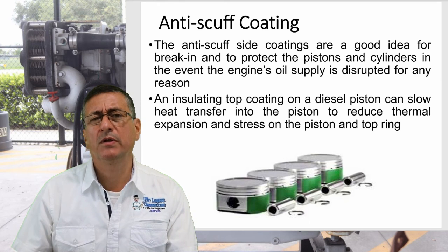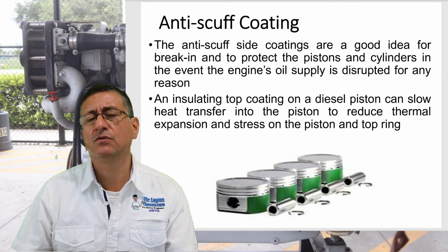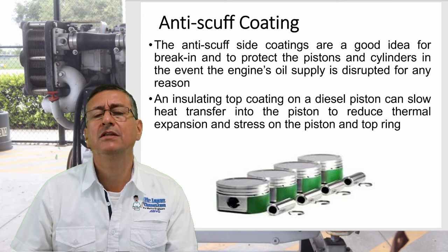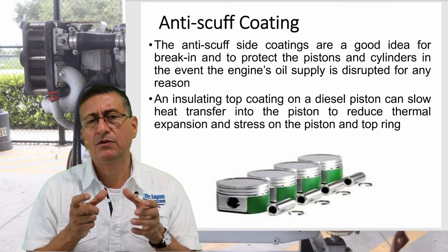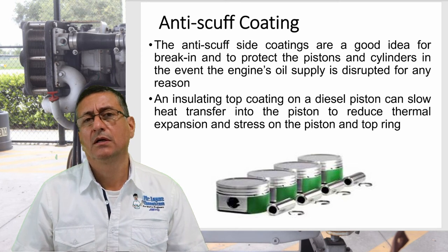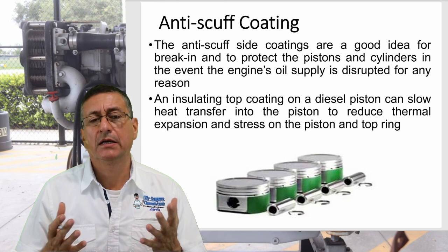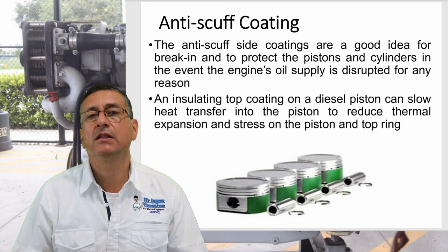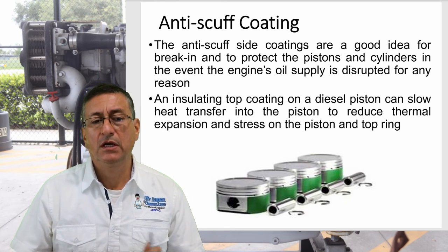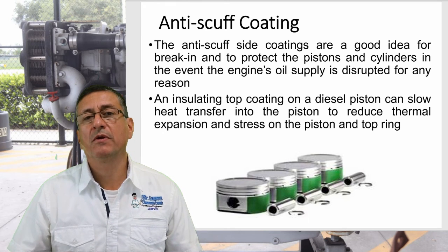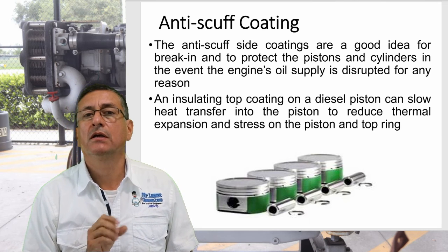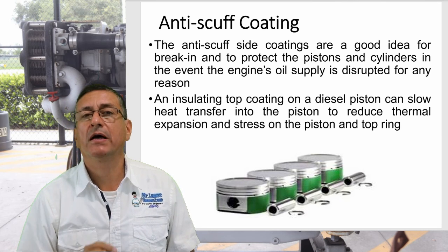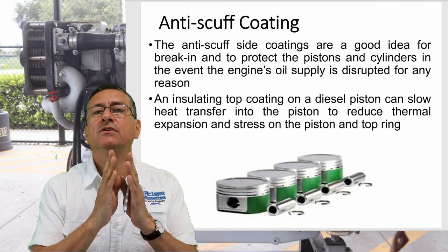Other important recommendation for diesel engines, for diesel pistons, is the lubrication in between the piston and the cylinder wall. The lubrication is other element that increases the durability of the pistons. Yes, the oil is coming from the oil jets in the bottom. It's a jet of oil that is sprayed in the bottom and enters inside of the piston.